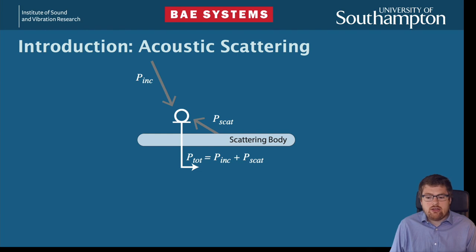Active control is a common method to reduce unwanted sound and vibration in a variety of situations, and would be a good way to acoustically cloak an object. We could design an active control system to use an array of sensors to detect the scattered acoustic field, and an array of loudspeakers to cancel it out. If the scattered pressure can be forced to zero, the object will be effectively cloaked, and will therefore not interact with the sound field it's placed in.